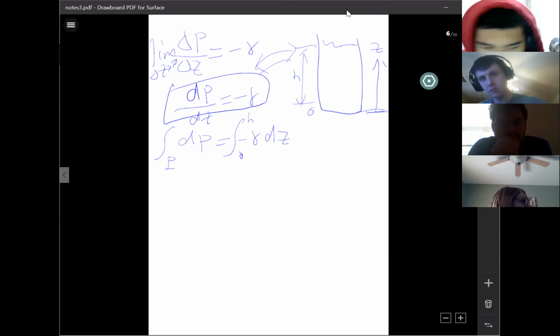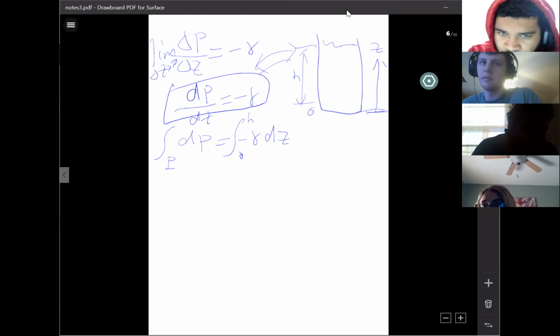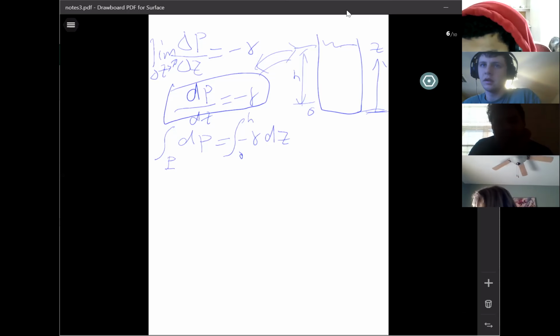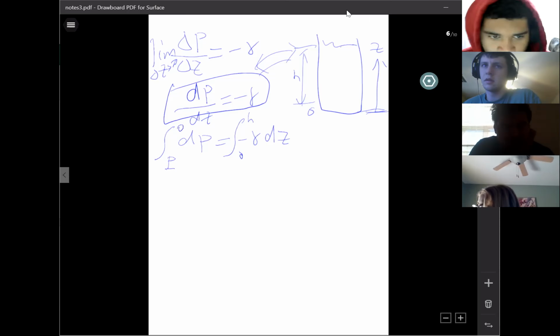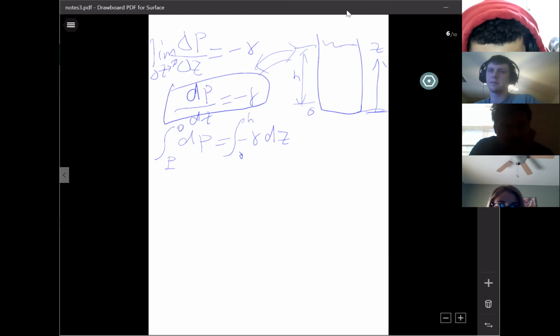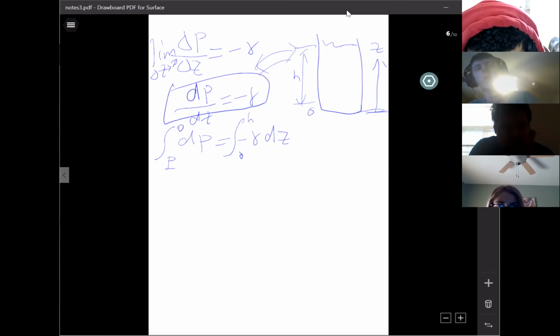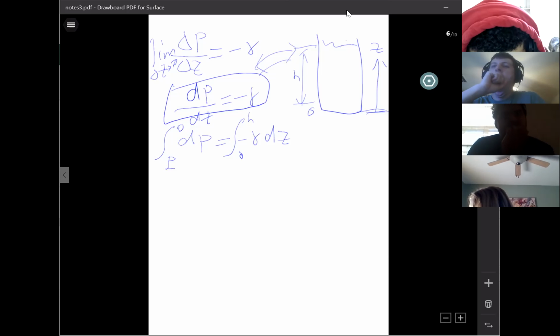No, in reality now, forget about the finite element. Atmosphere or 0? Atmosphere, yeah, 0, right? We use the gauge system. So is that what we do? This is the procedure for doing the integration. You have a dP and a dz, then you have the range. Be careful to be consistent about from where to where. You're going from the bottom to the top, 0 to H, then your pressure goes from the high pressure at the bottom to 0.